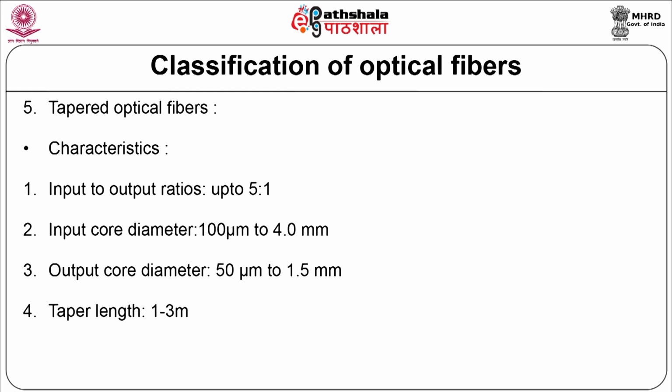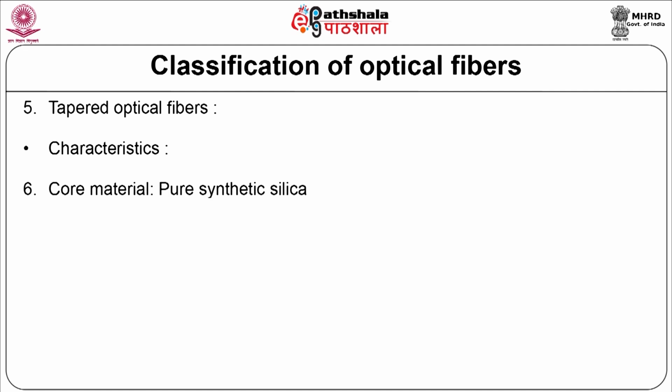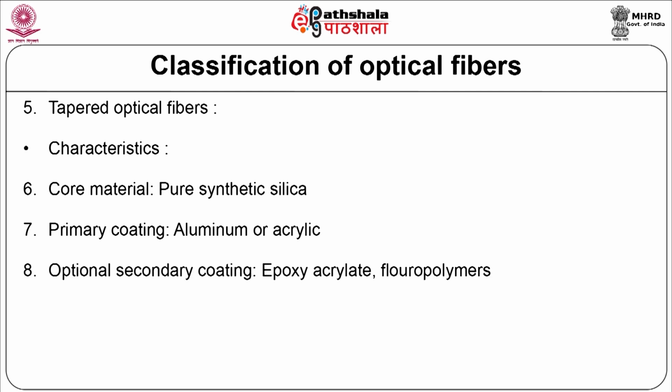Taper length is 1 to 3 meter. Total length is 3 to 10 meter. Core material is pure synthetic silica. Primary coating aluminum or acrylic. Optional secondary coating is epoxy, acrylate or fluoropolymers.